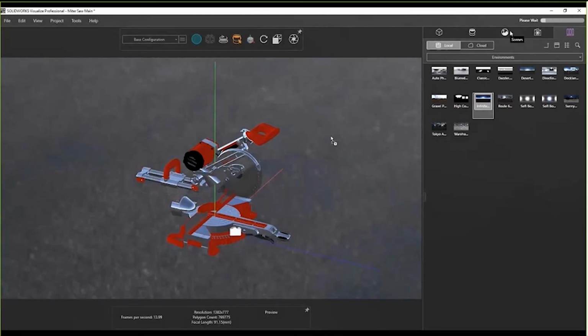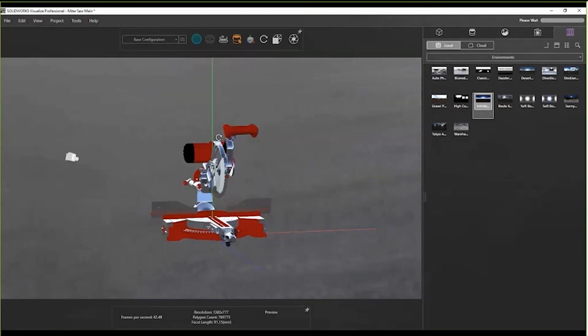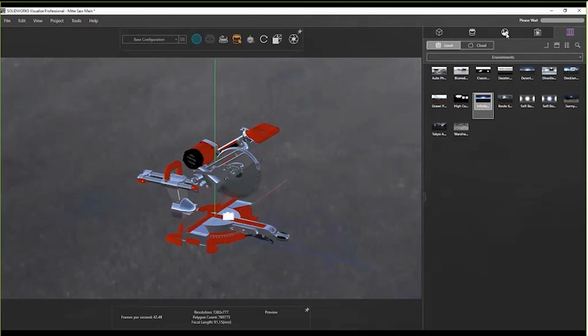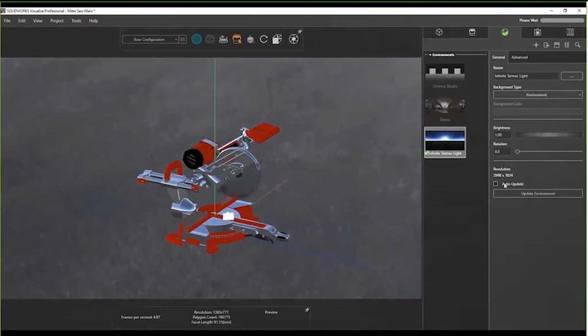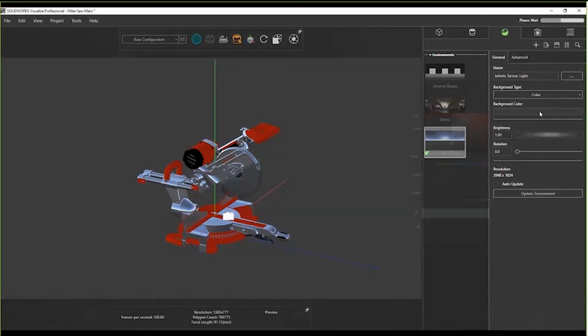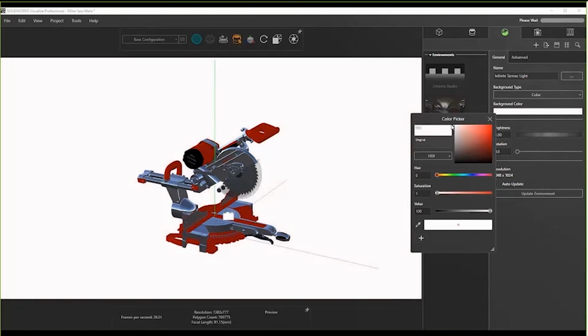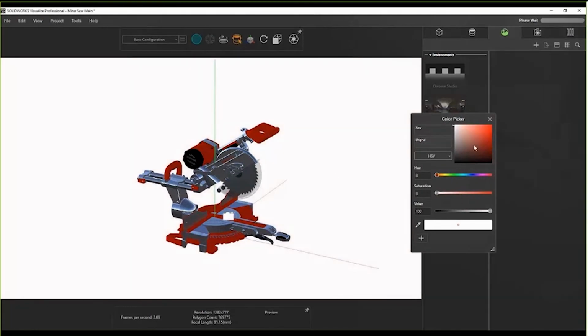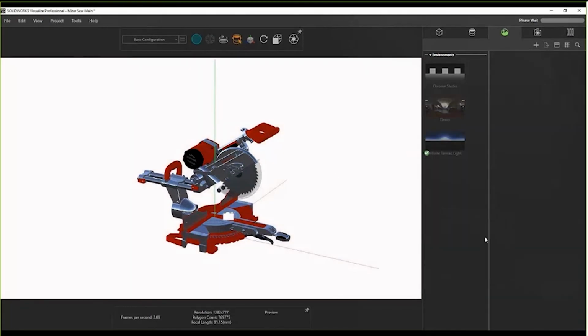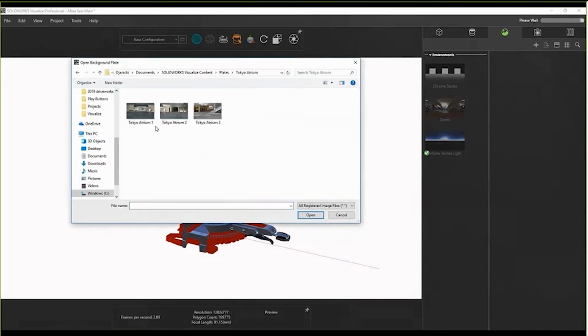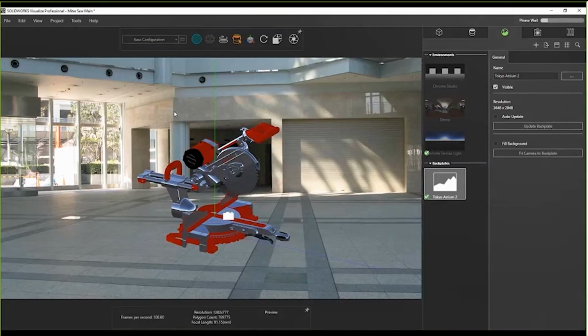So we've got these HDR environments that you can easily drag and drop in there. And what they're doing is they're adding in the lighting that's actually captured when the picture is taken, and it's putting in that background image. So I can turn that background image off and still have the lighting itself being applied to my part, right? So you can kind of see that blue shimmer on the part. Then I can put in whatever backplate it is that I truly wanted into here.